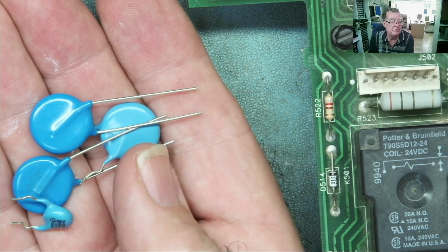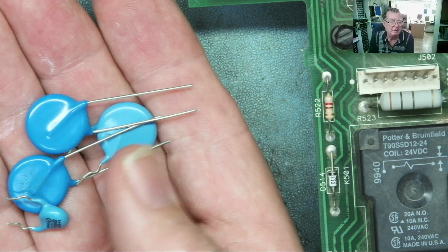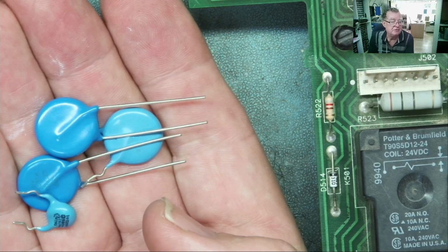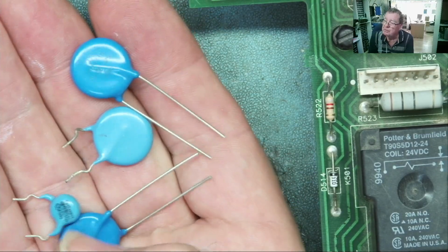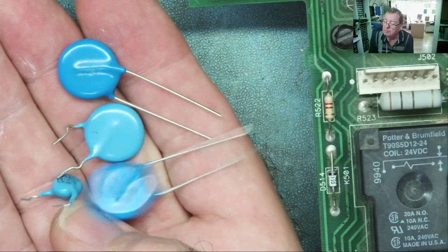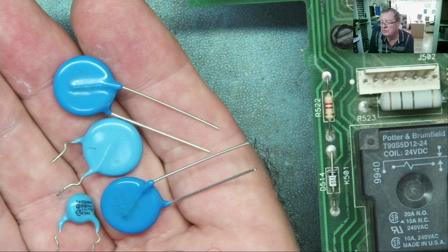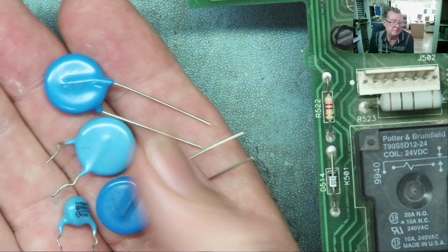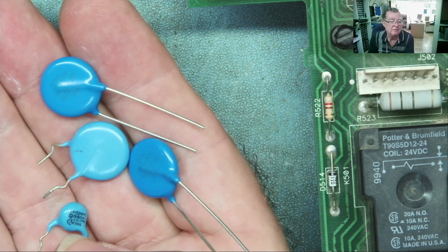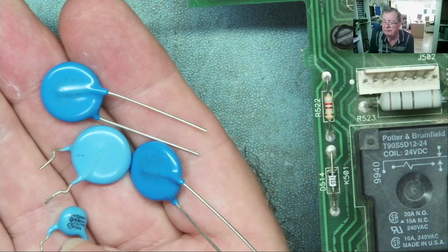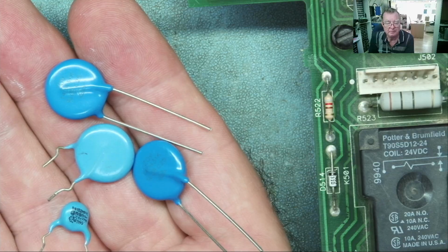And by doing so, if the voltage spike or surge lasts more than some milliseconds, these will just explode. So these normally fail by exploding. They look like capacitors, but they're not capacitors. They are MOVs. Okay? If these fail, normally you may find the fuse blows because these became short. And generally speaking, these fail because of some external voltage spike. So usually just replacing them will fix the problem.